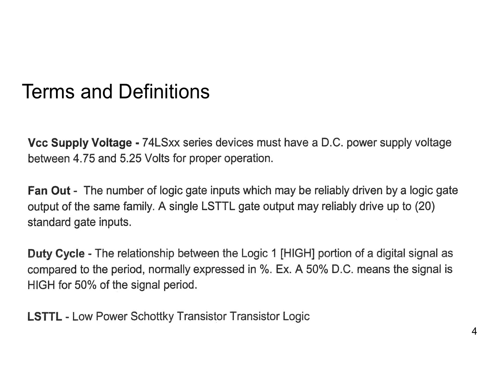Okay, all right. So if you had a logic pulse that looked like this, this is the high time, and this is the low time. The duty cycle is the percentage of the high time compared to the cycle, and this is one cycle. The way I've drawn it there, it's equal high and low times. It's equal to 50%, but it doesn't necessarily have to be that way.